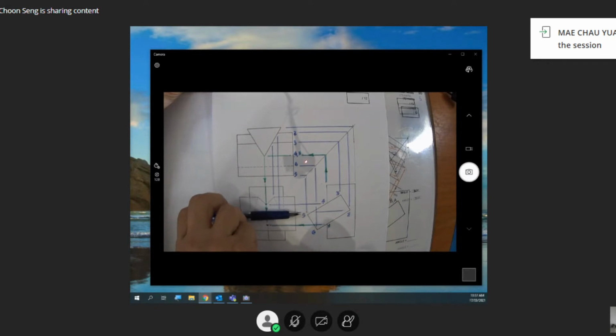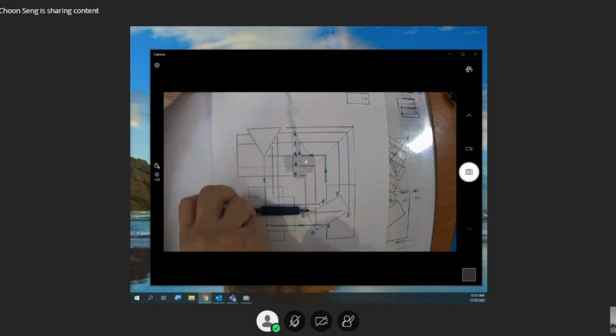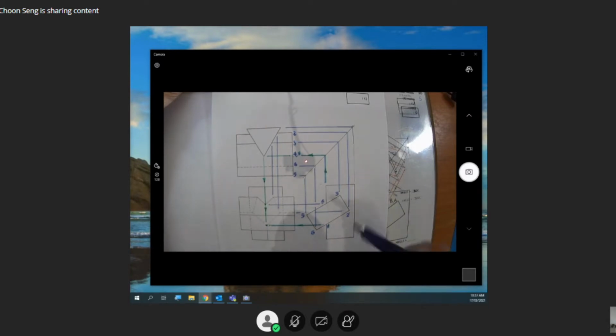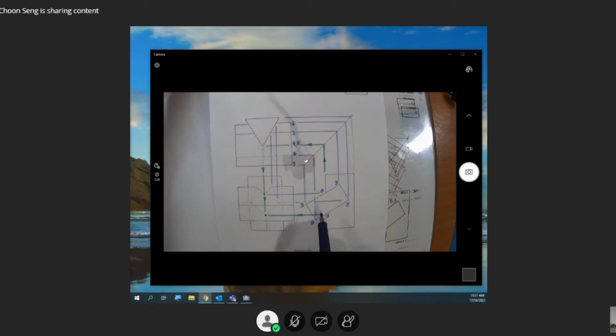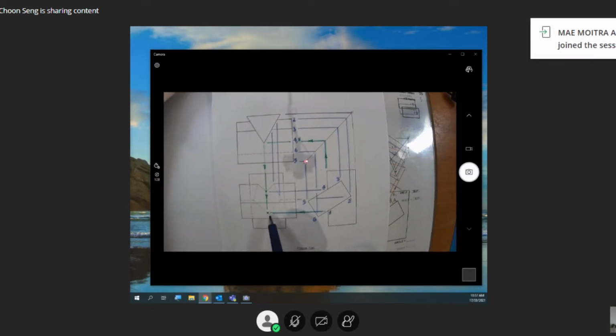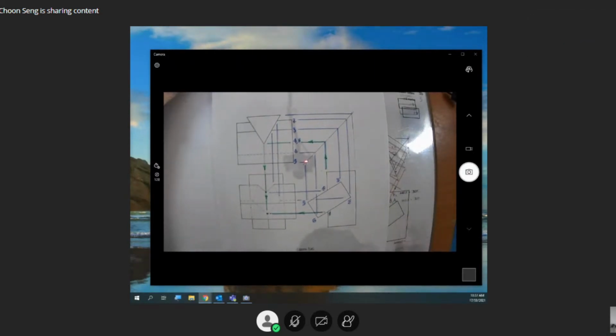If you are viewing from this direction, that is third angle, you view and you throw backwards, you would see your point 4 is here, so project backwards. So you get this point. Quickly label the point 4. Then point 1, you bring it across where this line meets, that's point 1. So label this one as 1. So far so good, right? Next slide.